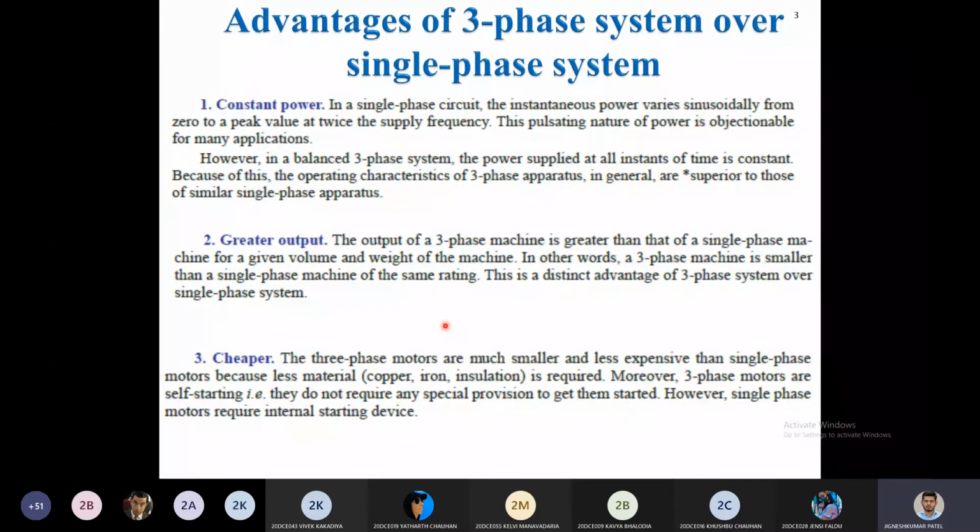We are not going into that deeper, but what I mean to say is, to start a single-phase motor, you require some additional jerk. That additional jerk can be provided using your hand or mechanical movement, or the other option is by changing the vector of your fan or any motor using a capacitor. So the capacitor starting method is used generally in single-phase motors. Mechanical motion is not used at any time. We only prefer the capacitive method.